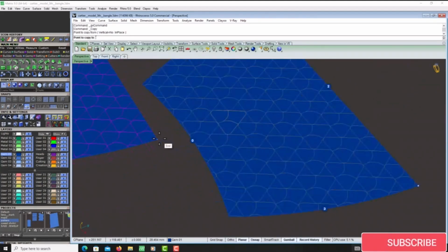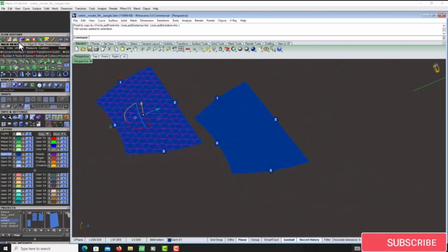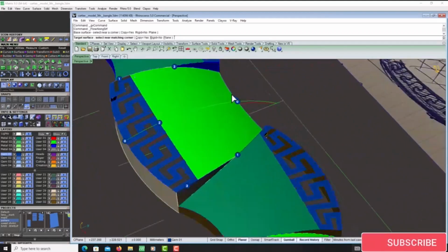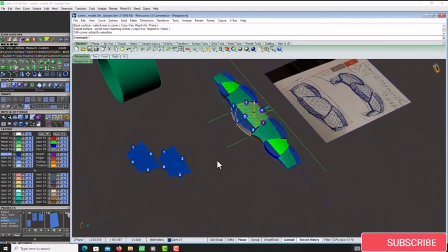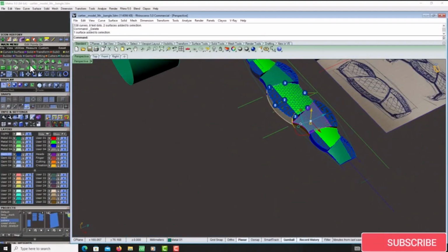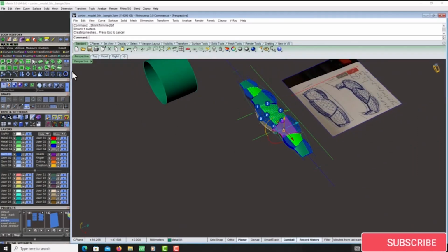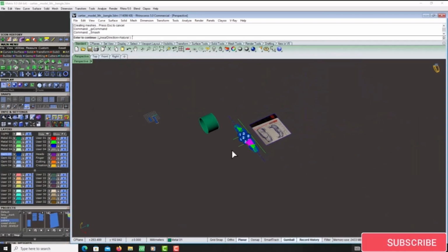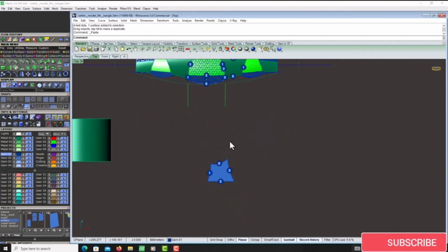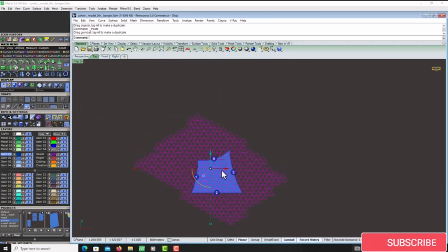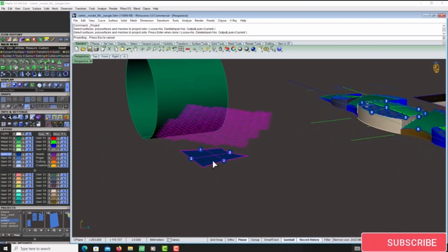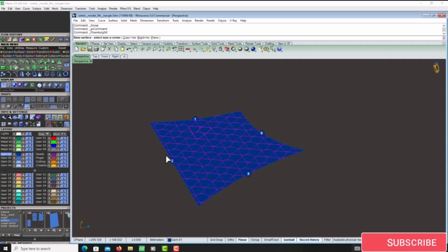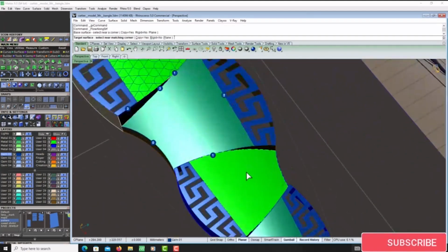You can click your projected pattern, okay, and click on flow on surface in transform, and then click on your projected pattern, and then enter, and then click on a base surface and enter, and then click on a target surface, meaning your green surface on a bangle, and then enter, and you have a pattern on your bangle surfaces.